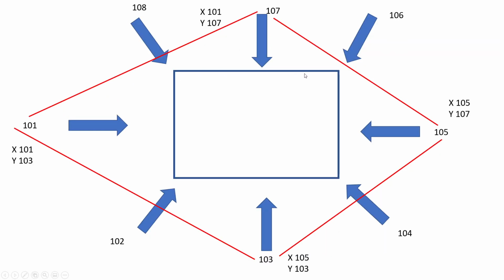See, this is one platform. These are the waves at 0 degree, 90 degree, 180 degree, 270 degree, and there will be 45 degree and other orthogonal directions also. Suppose this is load case 101, 102, 103, 4, 5, 6, 7, 8. There will be 8 load cases. Each and every platform will have a minimum of 8 load cases for a rectangular platform as per API.